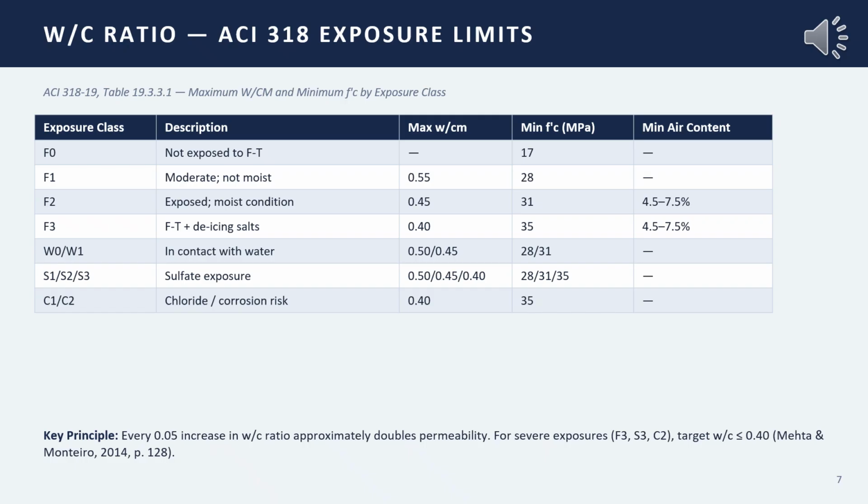So when you design a concrete mix, you must check every applicable exposure category and apply the most restrictive requirements. Do not pick and choose. Apply all of them simultaneously.